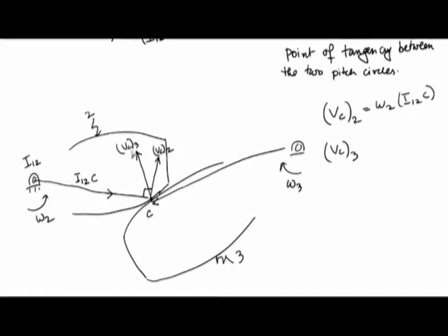So therefore there is sliding that is allowed at the point of contact, except when the point of contact itself becomes the pitch point. So the gears definitely have the type of action which is taking place between the gears definitely includes sliding between the two gear tooth, and the sliding demands that along the tangent of the two gear tooth the direction of velocity is not the same, right.